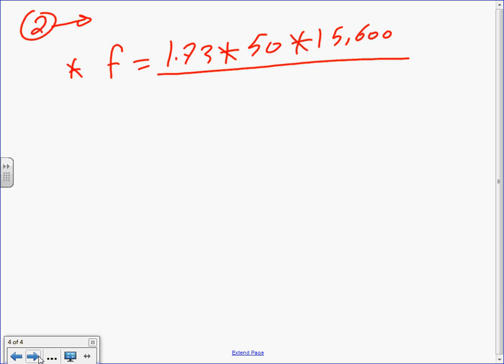The first decision that you need to make is: is it metallic or non-metallic? Is it copper? First of all, all these are for copper. Is it metallic or non-metallic? We're non-metallic, so go to non-metallic. Next, is your voltage 600 volt or less? Then you use 600 volt. Otherwise, if it's higher than 600 volt, you use the others. Kerry, does it make sense?